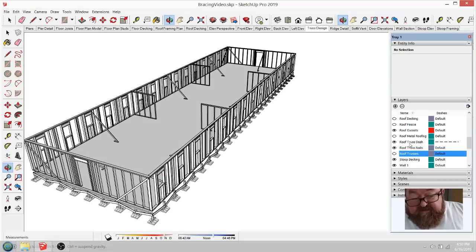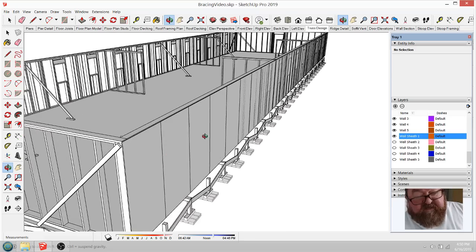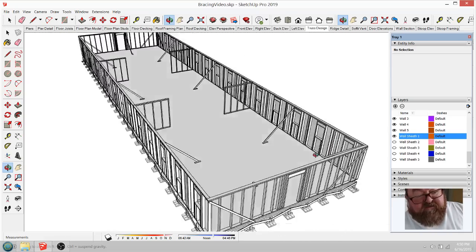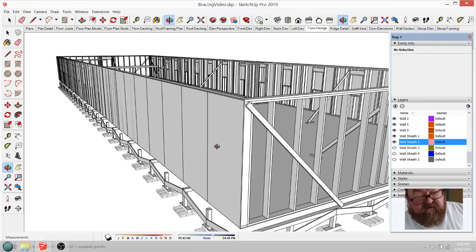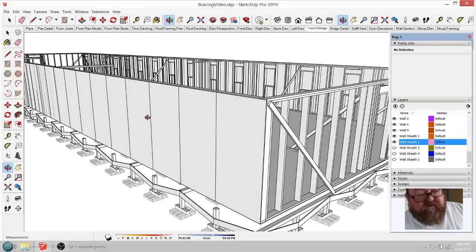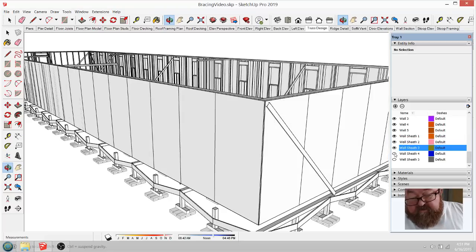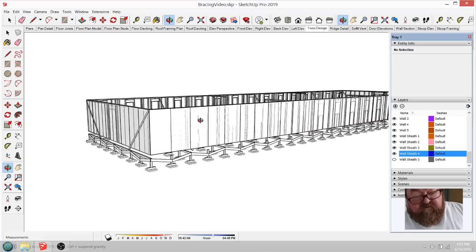Really, the ideal situation would be that you would sheet these walls. So if I can zoom in here, put the sheeting on these walls and just do it systematically. You want to get all the wall sheeting up. If for some reason you did have any windows, you don't want to cut them out. You just want to get your sheeting up, okay, as quickly as you can on all 4 of your walls.